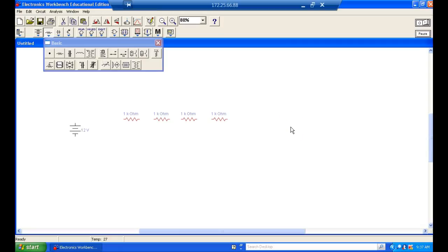You ever notice that? Because you're dealing with something that has very low resistance; it's usually tungsten. Tungsten has a pretty good R to it, but mostly it limits its current by heat. So when you first turn it on, it's got fairly low heat, so it gets a real shock, and then it heats up real fast and the resistance goes up. And then, of course, electric heaters. That's all an electric heater is, resistors. It's a resistive wire. It's wire, but it's not copper, not one of the real good conductors of electricity. So it's using nickel or nickel stuff like that, which has a pretty good resistance.